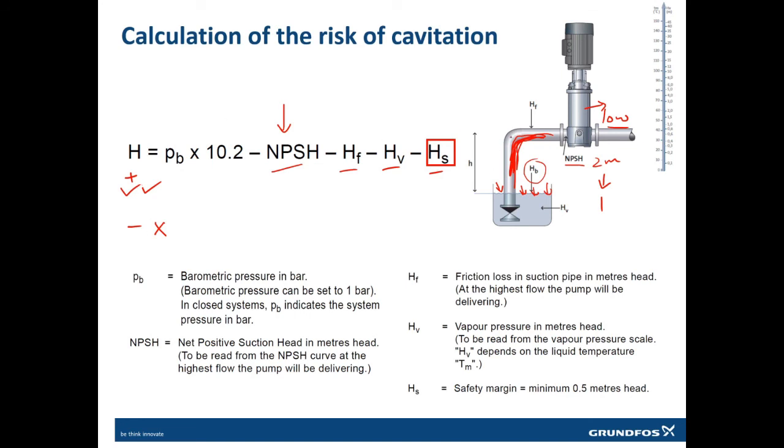How can you change the friction? Maybe you have a strainer installed here, remove the strainer. Or maybe you have a throttling valve installed here, remove the throttling valve. Because what will the throttling valve be doing? Increasing the resistance in the suction. You don't need any suction resistance.